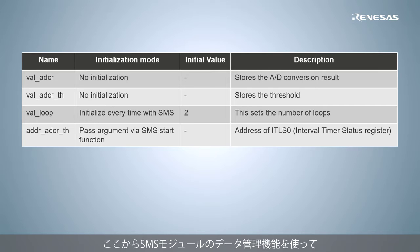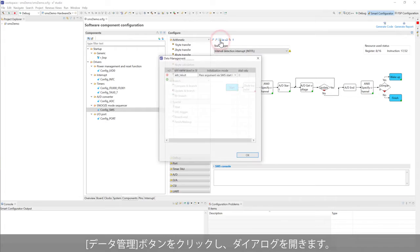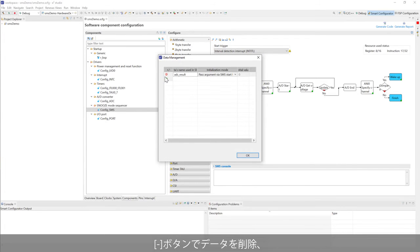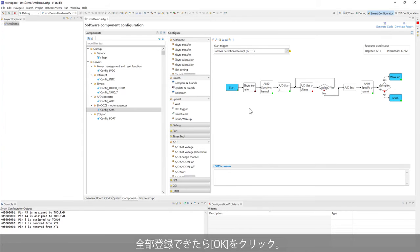Next, we will add the following variables, using the data management function of SMS module. Click on Data Management button to open the dialog. Click minus button to remove the existing data. Click plus button to add the data in the table. Click OK after adding all the variables.